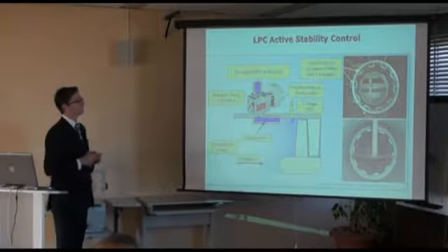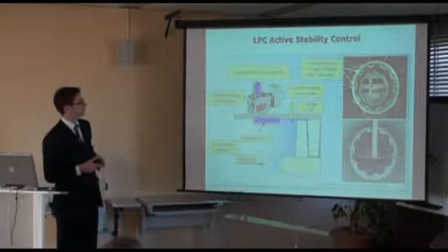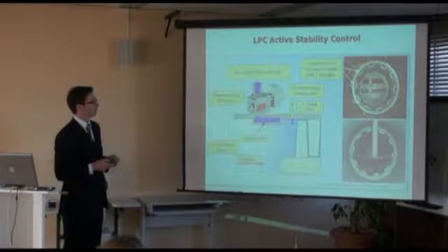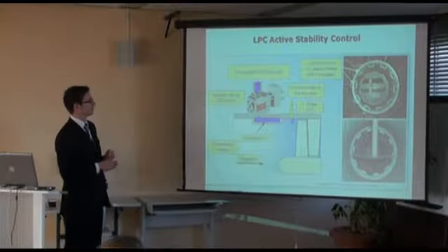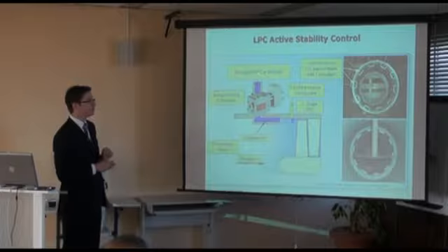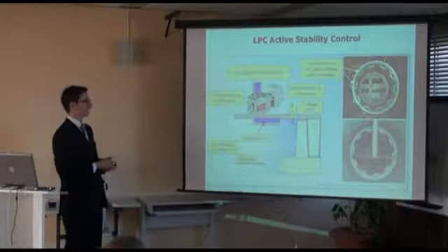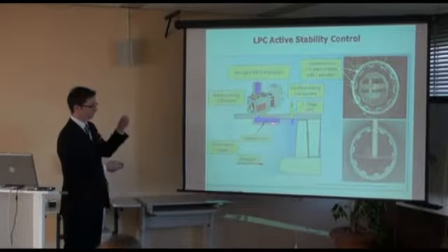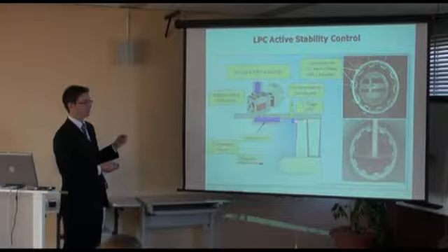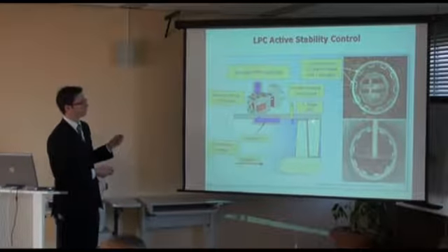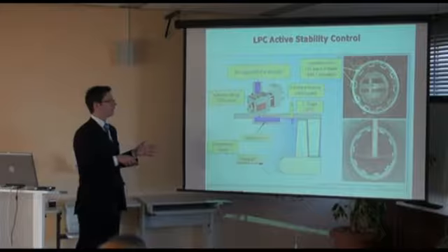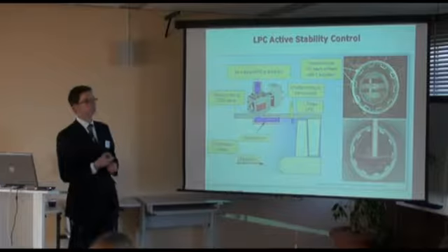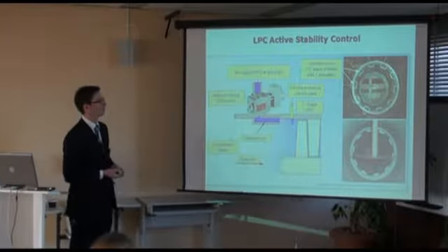This is an example of active stability control with tip ejection, which was done at the University of the Armed Forces in Munich. They took a Larzac engine, took air out of the HPC, or took simply shop air, which you do in the laboratory, blew it into the front phase, into the tip gap region of the low pressure compressor, and therefore stabilized the flow. And they could also sense the pressure signatures before the stability event.